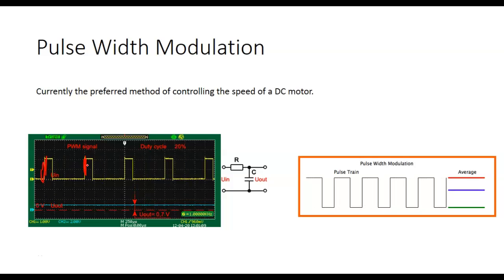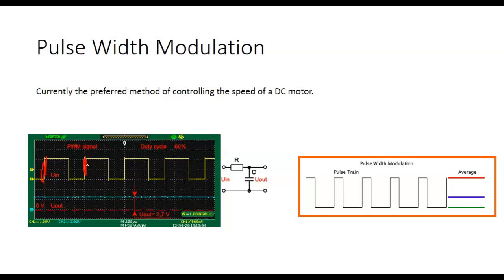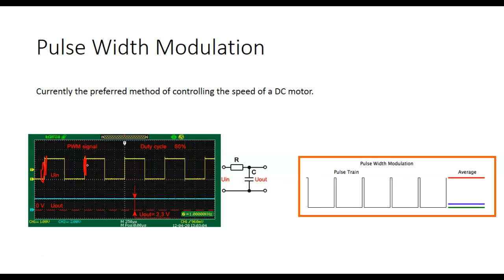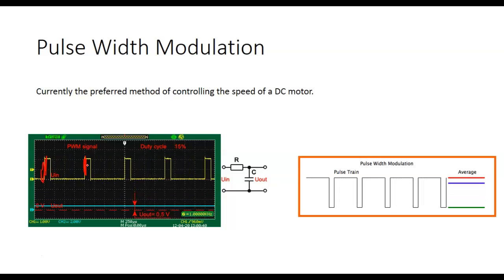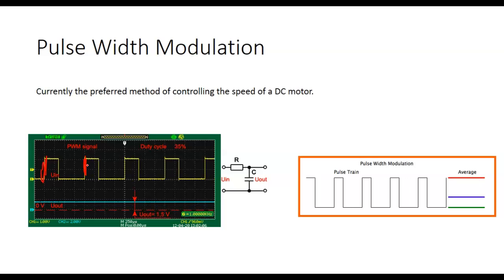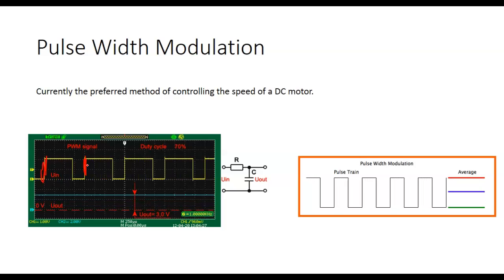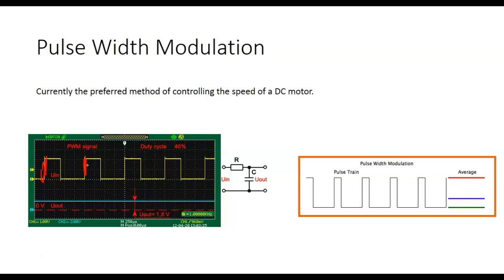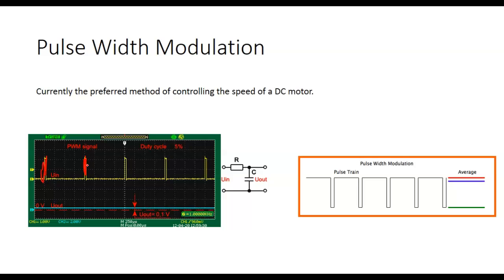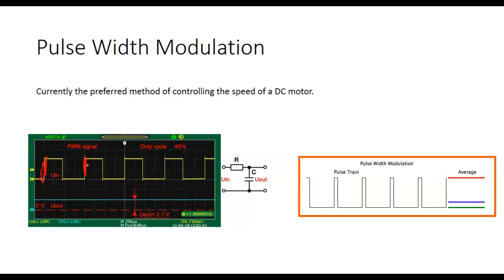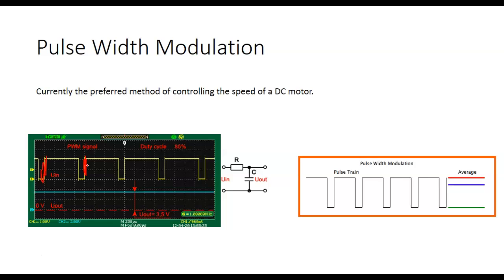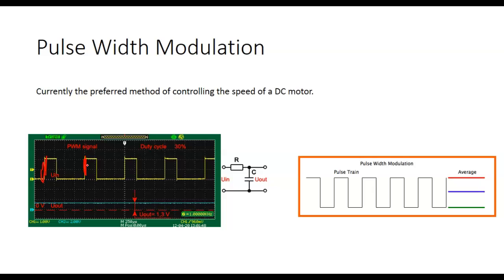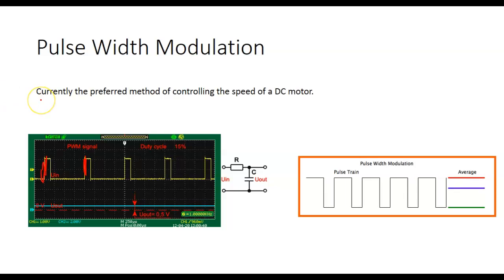In fact, this guy right here supports pulse width modulation. So this PLC supports this. Most PLCs actually support pulse width modulation, where we could send a code into the circuit and it would do whatever pulse width we wanted to control the speed. I could do this, but I'll probably try to hook it up for next class. I'll probably run it off this function generator instead of my Arduino. I can't find the programs to run it.